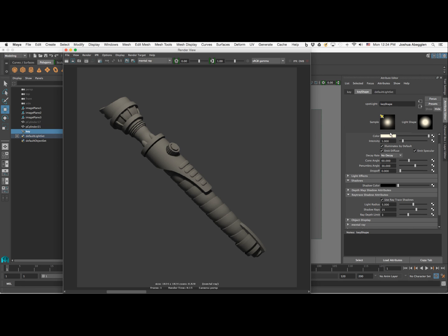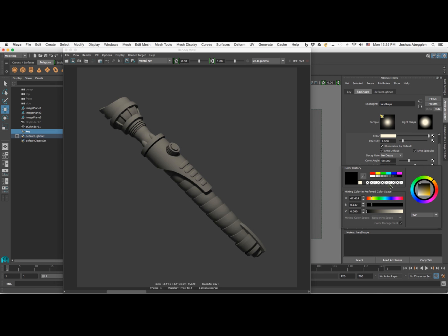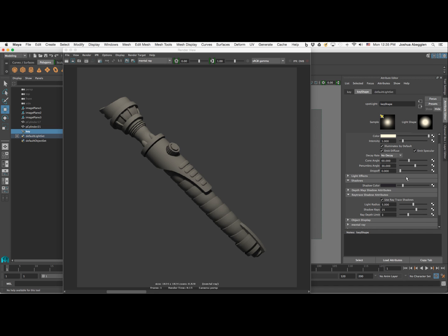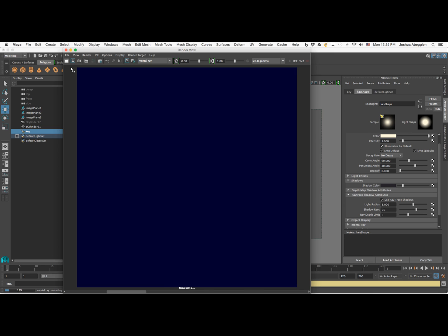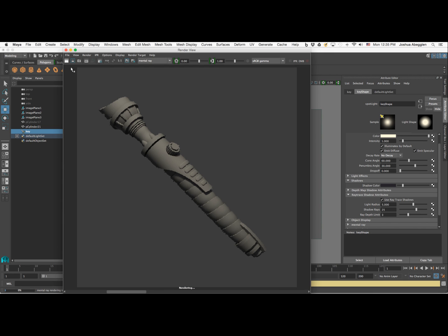If you have a warm temperature to your light source, your shadows will actually be the complement of the color of the light source. So because we're dealing with a little bit of a yellow-orange right here, we would be dealing a little bit with a blue-violet. All right, so I'm going to bring this down around into this area. I want to keep it relatively desaturated and relatively dark. If it becomes too saturated, it's going to look a little funny when we render it. It's just going to be pushing a little too much contrast into the model.